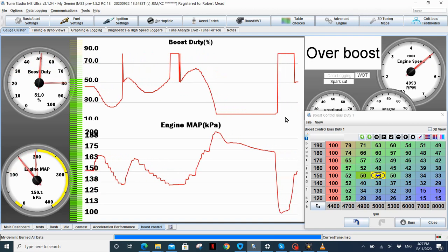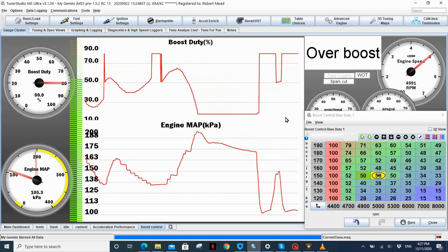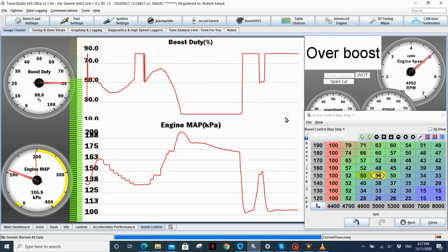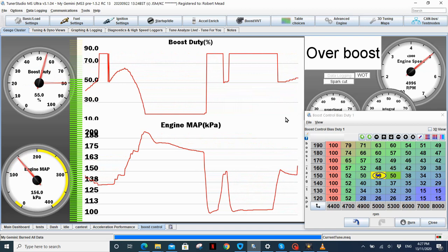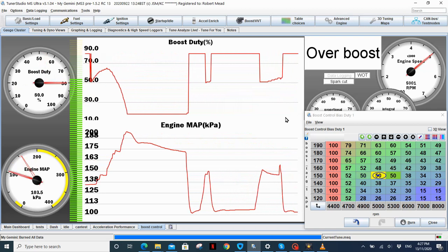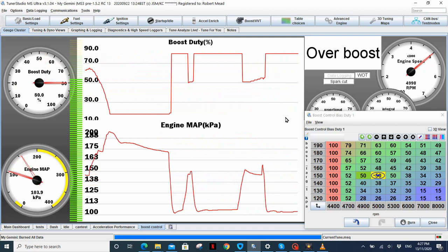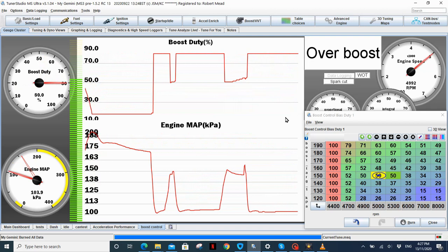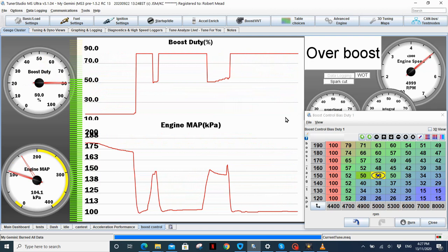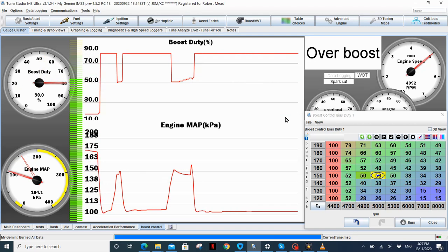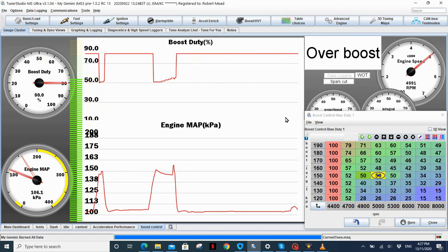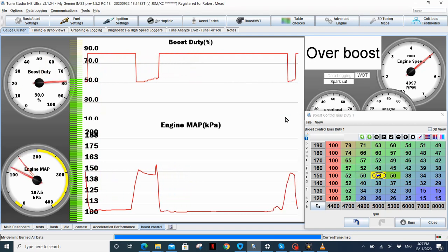Now there's a few things going on here. So it'll jump into the PID loop at the value in your bias table. Then the offsetters of the bias table, as you move around that table, will offset where it's at. It won't necessarily run the same value as in the table, because any changes the PID has made will move it around. But I'll try and show you.